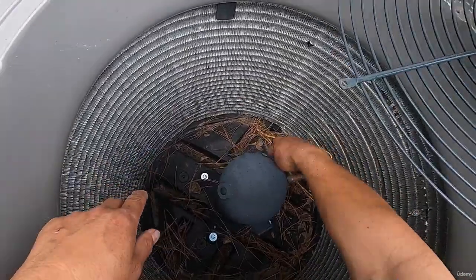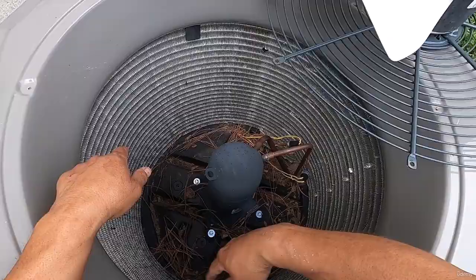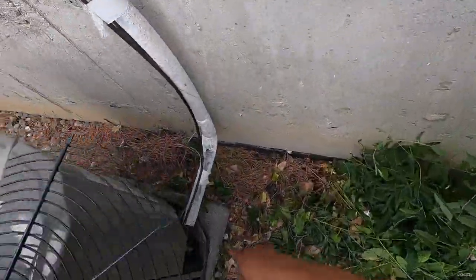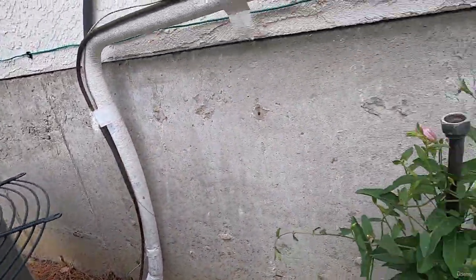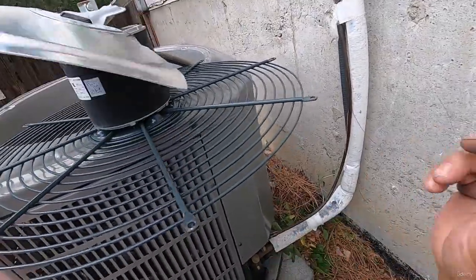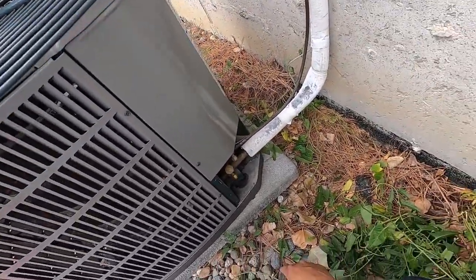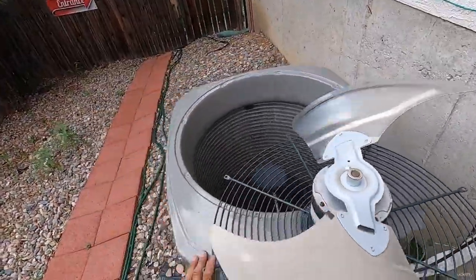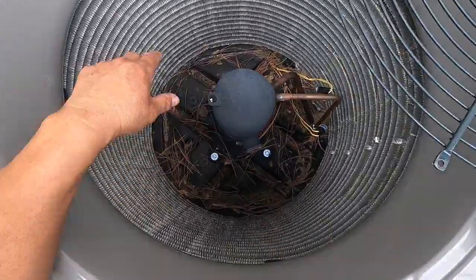So it'll bring it in, compress, comes out through the coils, and then it goes back through the high side and then back to the evaporator coil. And again, it just makes a big loop and it just keeps pumping that Freon. So I wanted to show you the major components of that. And we're going to cover troubleshooting of the compressor.